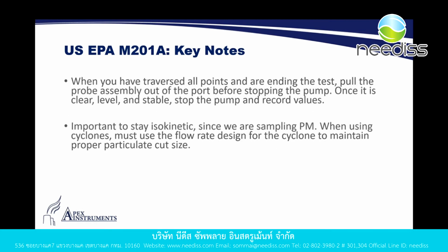When you have done all of your testing over the stack and you pull out the probe from the stack, you stop your pump. Once it's clear, level, and stable, stop the pump and record all your values. So you're actually going to stop your pump after you've pulled out the probe and all of the values become constant once again from moving the stack, from moving the probe.